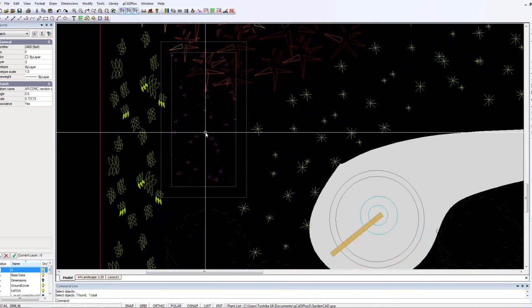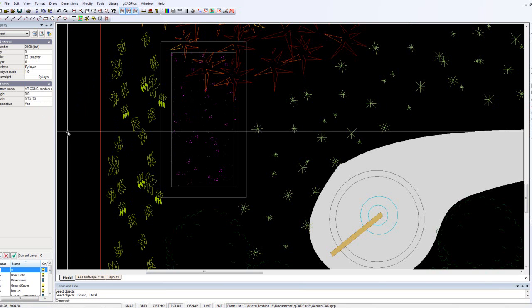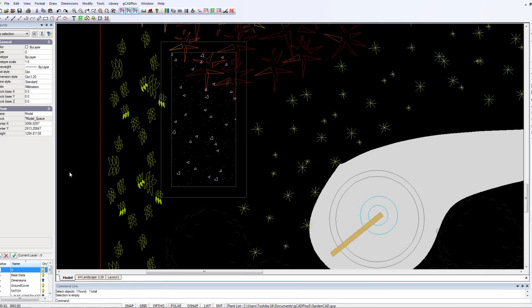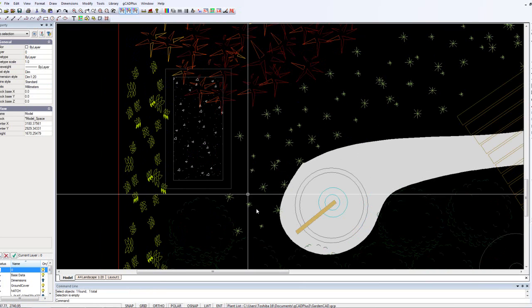The key issue is to be careful with the scale. You can see the scale over here. Key issue is to keep the scale to a value reasonably low. If you choose a value that's going to put a density of 3 and 4 and 500, the CAD software will go off and spend all day long. It may even crash as it tries to put many entities into the drawing. So hatching can be done in that way.